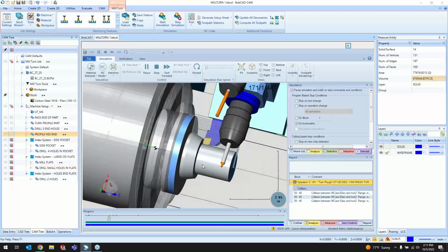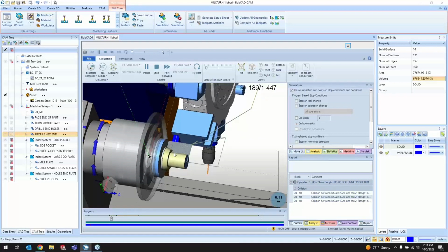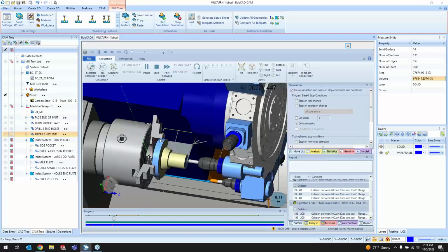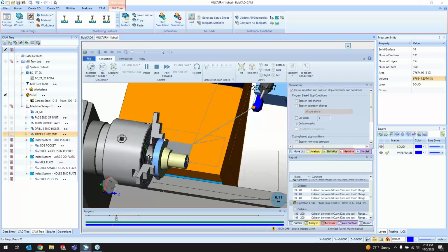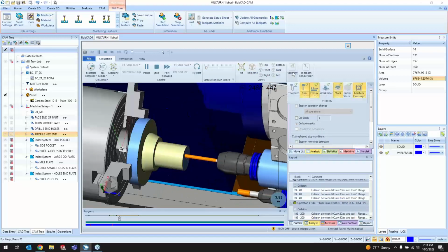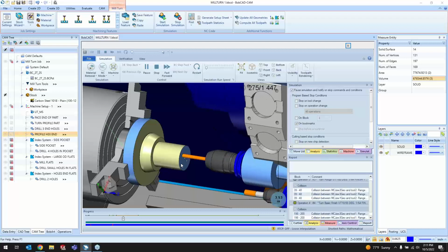But here's the roughing of the outer diameter. The finish pass. Might hit the spindle again here. Yeah, we'll want to turn off that, or create the toolpath so it doesn't go all the way across the stock. But anyways, I'll turn off the toolpath here. Under visibility, turn off the toolpath so we can see the drilling operation, and then the profile cut.